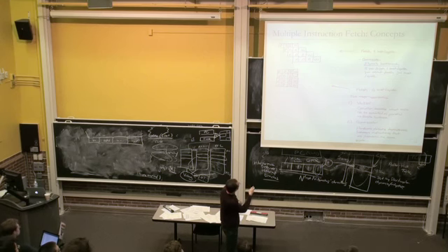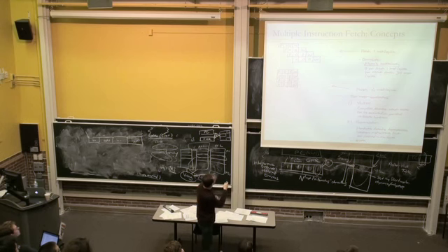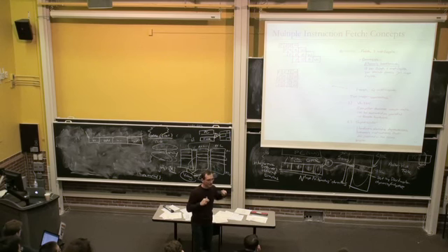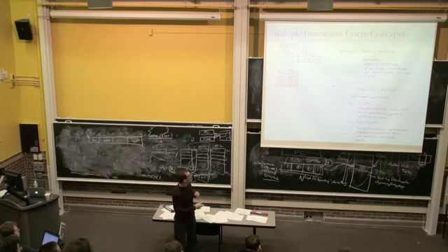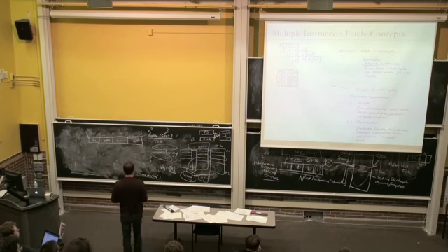So the idea of multiple instruction fetch is that we want to make the throughput of a machine much larger. Why don't we fetch more than one instruction per cycle? This is an example where you fetch 4 instructions per cycle. Of course, you need to somehow replicate the pipeline in this case, because you need to be able to decode, execute, and store results for 4 instructions per cycle. But this significantly improves your throughput, and this is what modern machines employ.